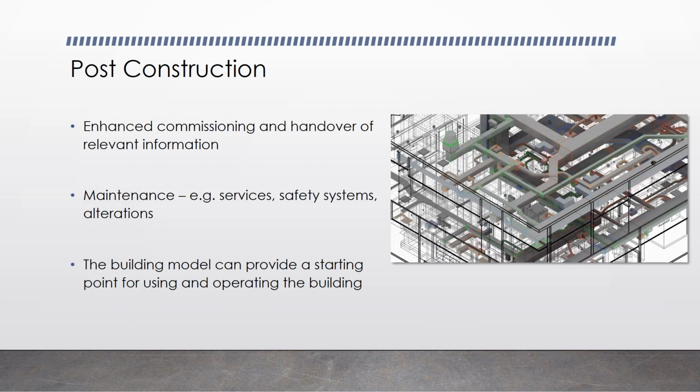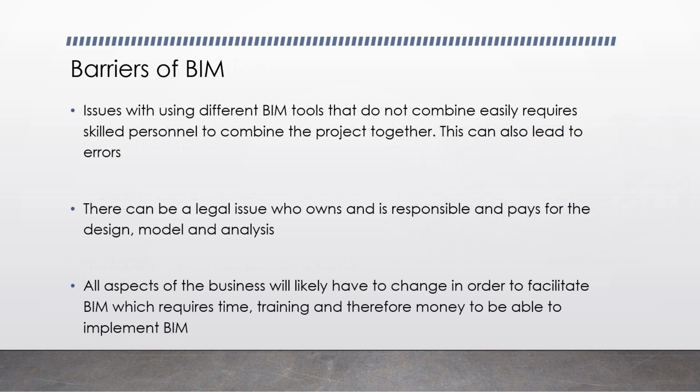Some of the post-construction benefits are that it's more enhanced for commissioning and handover. It makes it easier for both the client and the contractor to get the correct information handed over. This also means that the client can have the relevant information for maintenance, such as for safety systems. And it also means that the building model can be used by the client to show how to operate the building effectively. However, there are some drawbacks to BIM.